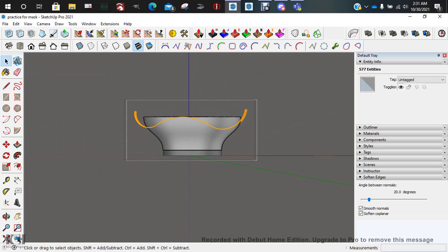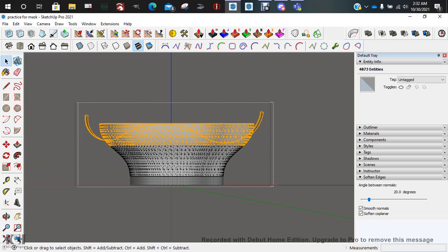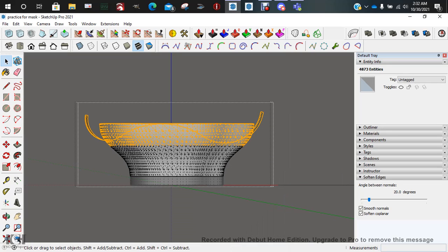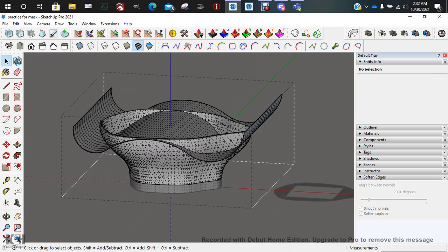Then I'm going to look at it from this side and I'm going to left click and drag so it's the dashed line. First turn on hidden geometry, because I don't want all the geometry selected. I only want that much. And you're going to go right click, intersect faces with selection. Now this can take its time. So, well, that time it didn't.